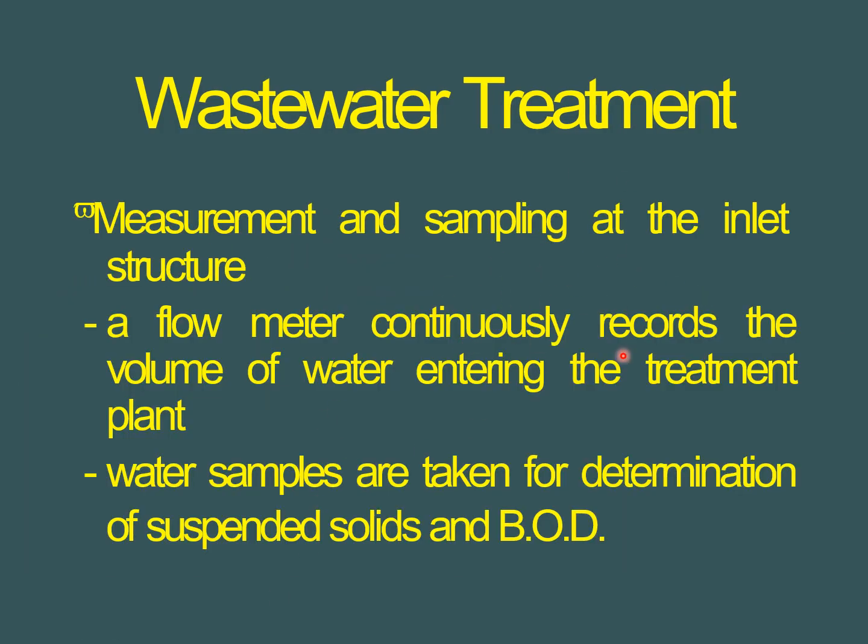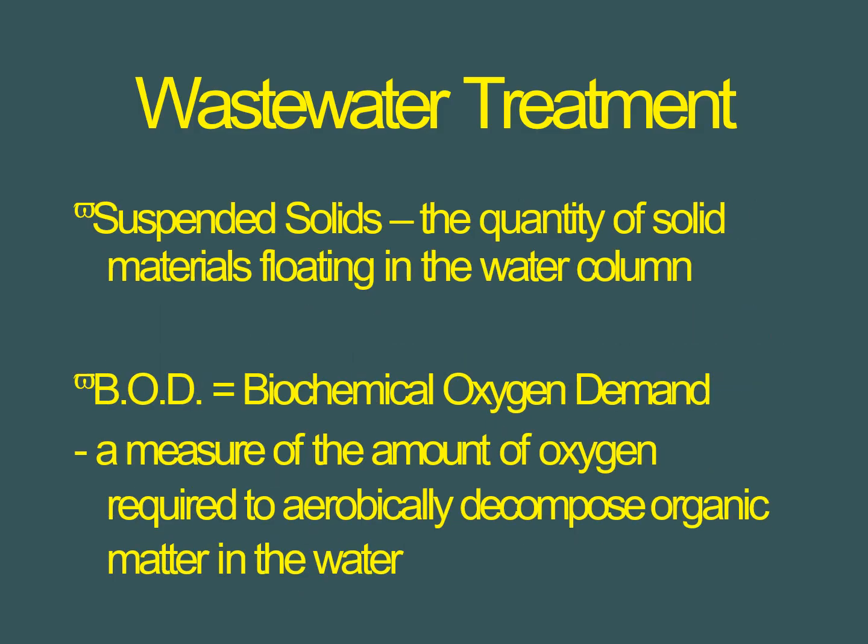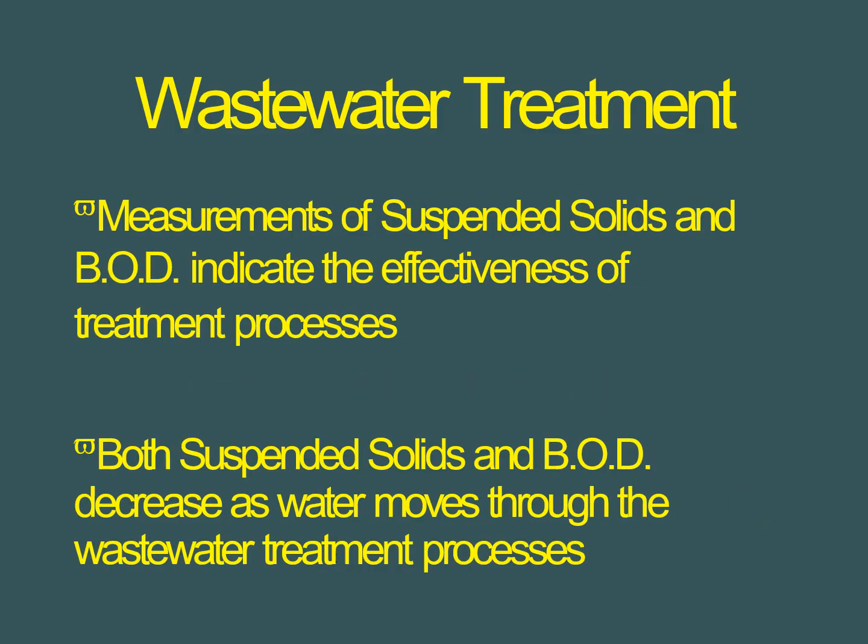For measurement and sampling at the inlet structure, a flow meter continuously records the volume of water entering the treatment plant. Water samples are taken for the determination of suspended solids and BOD. Suspended solids are the quantity of solid materials floating in the water column. BOD, we know very well, is biological oxygen demand, a measure of the amount of oxygen required to aerobically decompose organic matter in the water. Measures of suspended solids and BOD indicate the effectiveness of treatment processes. Both decrease as water moves through the wastewater treatment processes.